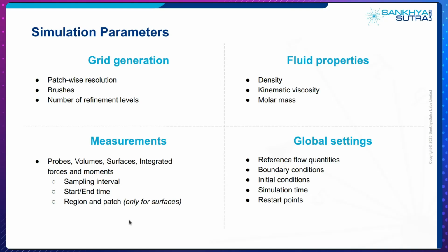And once you're done with this, you can set up the initial and boundary conditions. So this will be walls, inlets, outlets, any symmetry or periodicity conditions and things like these. And you define your reference quantities through the initial conditions. So the initial condition that we support right now is for pressure, velocity, and temperature Dirichlet conditions.